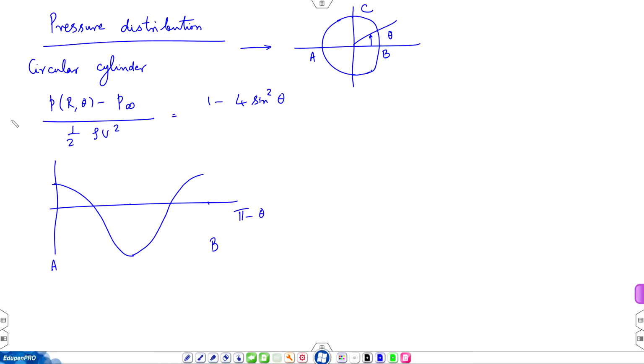So, this is what is Cp? Cp we called it pressure coefficient, just continuing with the notation of Cl, Cd and now Cp, that dimensionless quantity. This is the pressure variation over the surface of the cylinder. This is the result that gave us 0 drag.